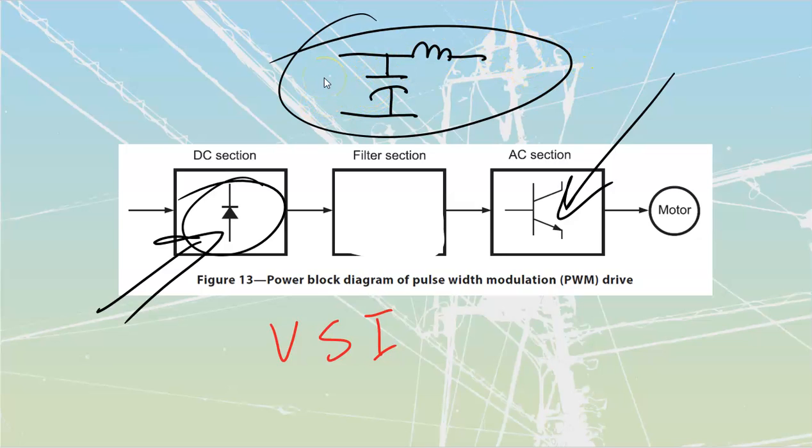There is a more complicated type of VSI drive that is called the Flux Vector Controller. The Flux Vector Controller basically monitors the amount of consistent current going out to flux the stator windings compared with the pulsating flux that's going out, which must be transferred over to the rotor windings. And it sends out different values of voltage, different values of time to maintain a consistent flux on there. It monitors both the rotor and the stator flux independently, and then it can maintain a much better amount of torque, which is really the big reason that we like to see those flux vector drives.